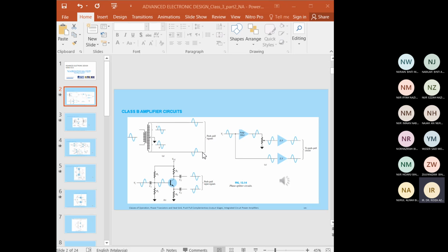input signal, okay? Meaning that the phase inversion in terms of polarity is obtained by using the tap that you can see here, a kind of transformer coupled amplifier. The opposite polarity input can also be obtained using op-amps, which have two opposite outputs. For example, by using a few op-amp stages in order to obtain two opposite polarity signals.